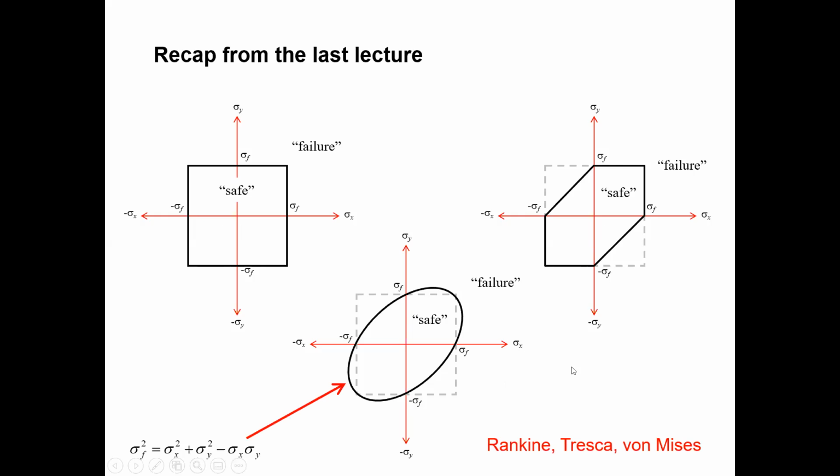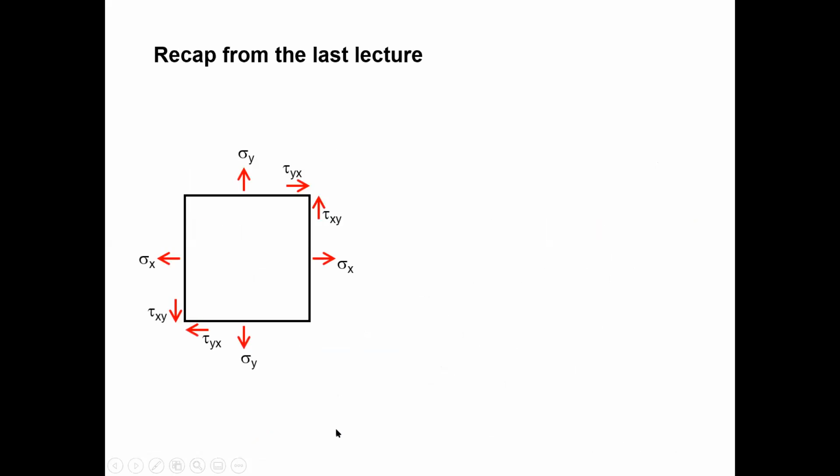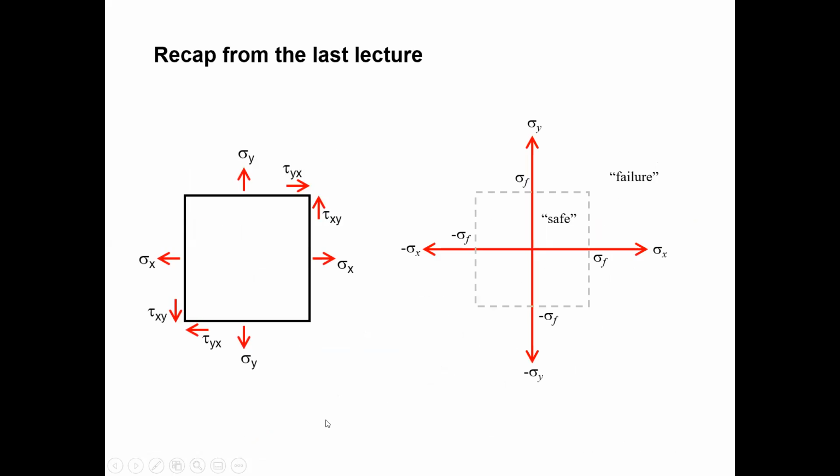And then, yeah, this is the equation, equivalent stress. So you can use this equation if shear stress is absent. So you need to find sigma 1 and sigma 2 here. So you can't apply it with the shear stress. You need to eliminate shear stress. Okay.